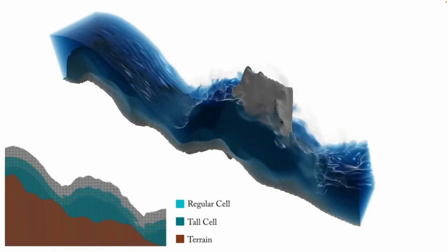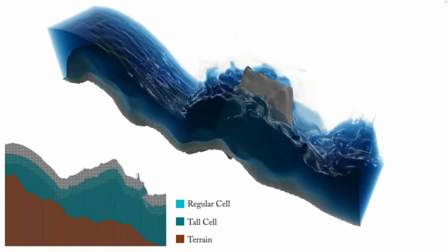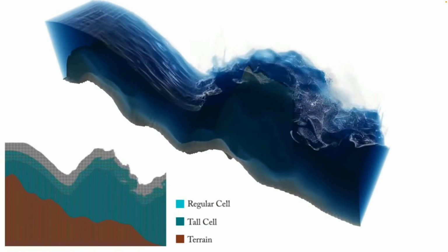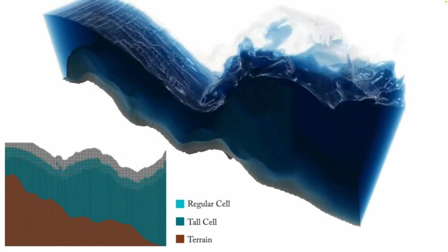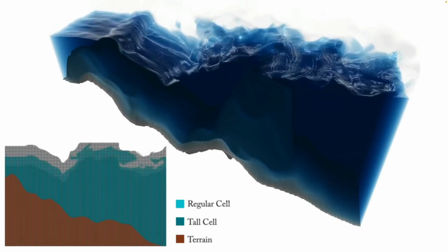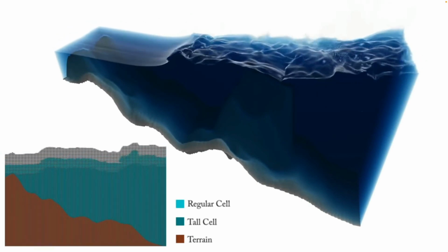They're much more difficult when you have a free surface involved, because you don't have a closed boundary to your system. And you can see on the bottom left-hand inset that the mesh kind of grows as the free surface grows, to be able to accommodate the fact that you have little beads of water breaking off that have to be accounted for in the overall mass balance equation, right?